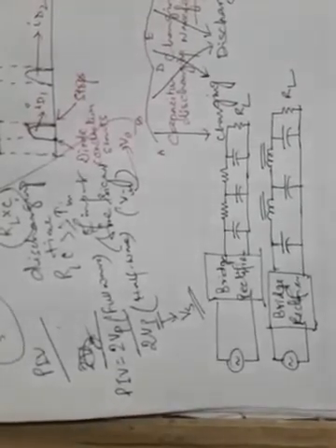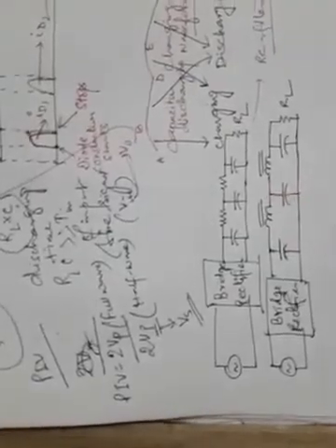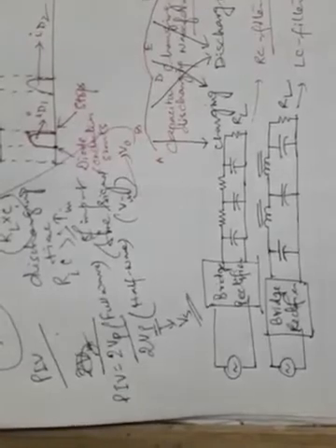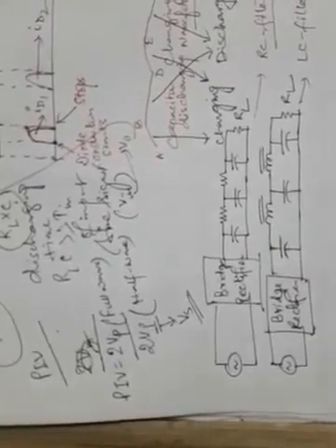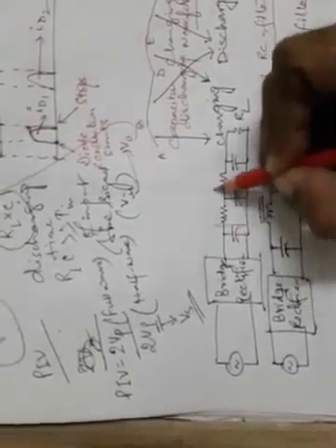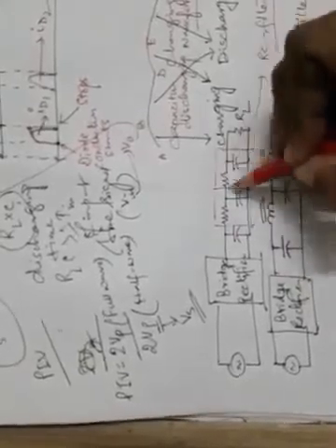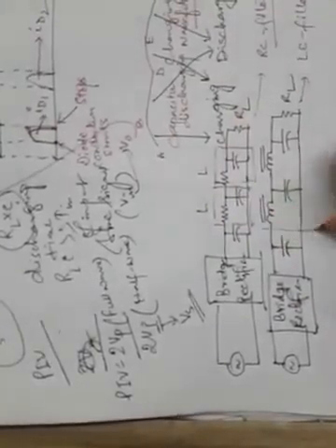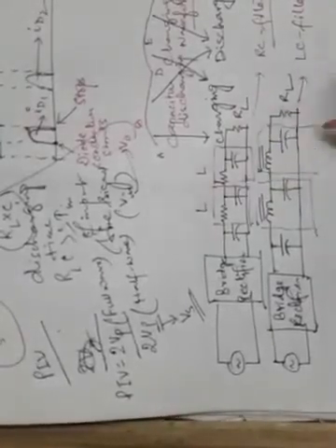So in the first case, we can say that this is an RC filtering scheme, because the filter comprises a resistance in series and a capacitor in shunt, and this is an LC filtering scheme, an inductor in series and a capacitor in shunt. Initially a shunt capacitor input filter, which we have just seen, is connected, and we can say that this is an L section filter and this is an L section filter. So this is two series connected L section filters comprised of RC, and these two are series connected L section filters comprised of LC.